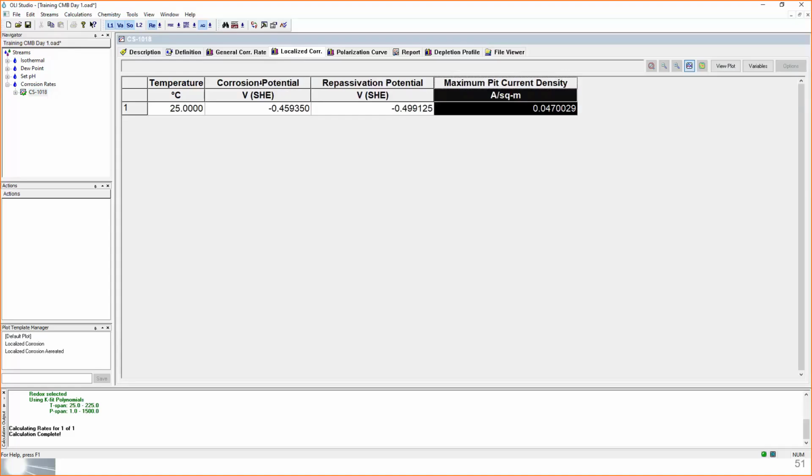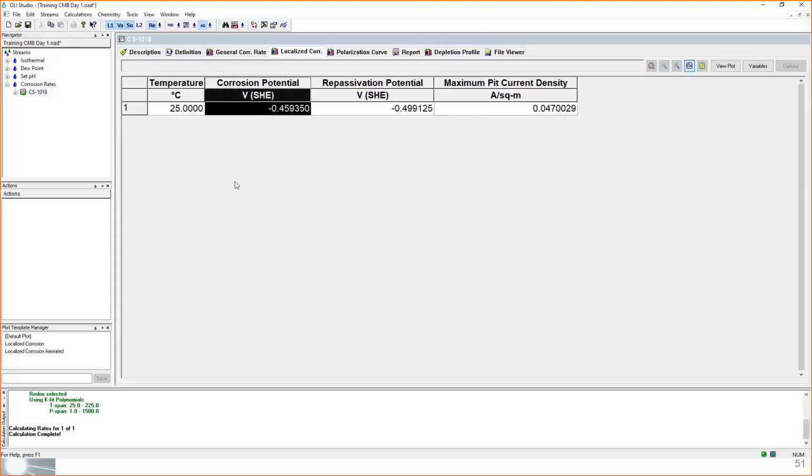Okay, so corrosion potential is, again, you have your electrode surface in your bulk solution, which in this case is sodium chloride and oxygen. And we have left the sample there, and it has reached, not an equilibrium, but it has reached a rest potential with this bulk solution. And this is the potential that is measured on the electrode surface. So corrosion potential could be the same as open circuit potential, OCP.